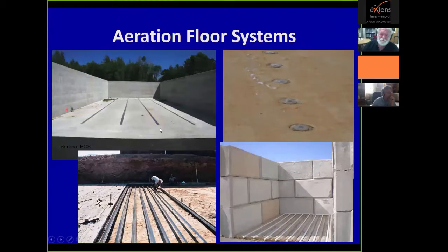In the upper left, we see a traditional rectangular concrete trench. This is formed by building essentially a box in the formwork and then pulling the box out as the concrete sets. We have the spargers that we saw on the previous slide here on the upper right. On the lower left is a method I used at one of my facilities by taking angle iron and turning it around upside down to create a V-notch, which you see here in the concrete, and the V-notch carries the pipe.